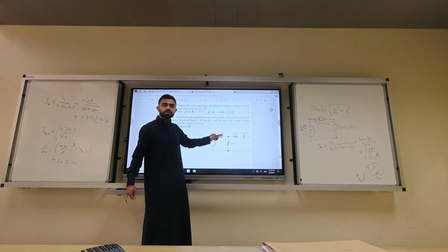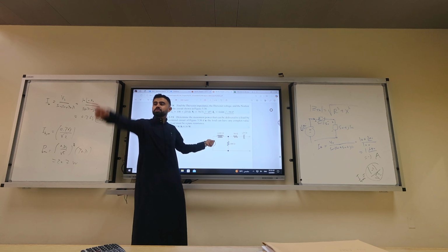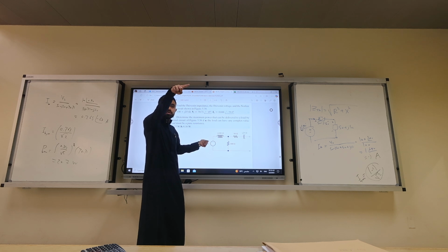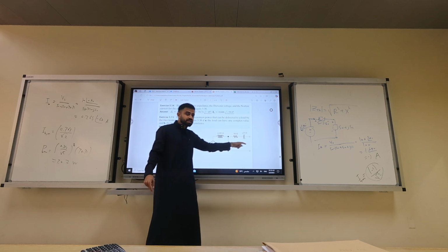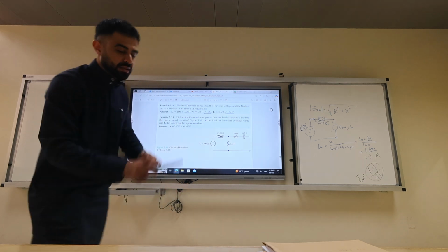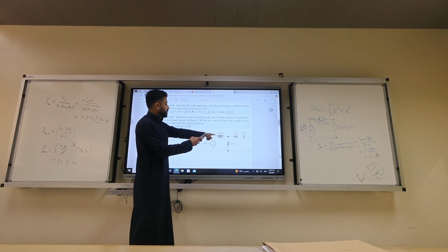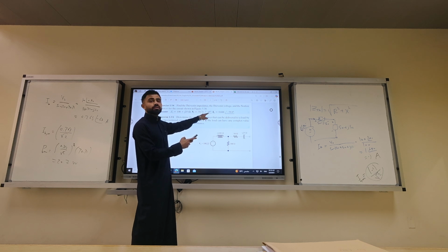100 over J100 plus 100, times. Get it? Do you see the VDR? Fawaz, do you see the VDR? Hatem, do you see the VDR? Why is it a VDR? Because of the same current. For the open circuit, 100 is in series with J100. Let's do it. What's V Thévenin? 100 over 100 plus J times 100, times 100 angle 0. And you will get 50 minus 50J, or 70.71 angle minus 45.